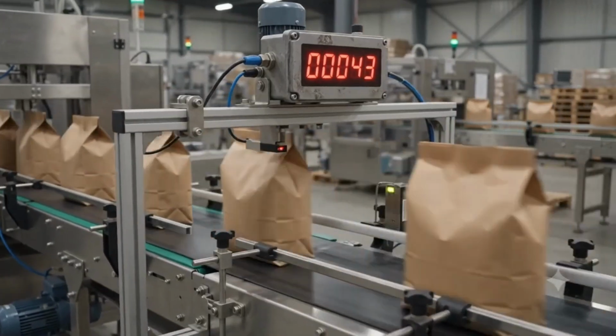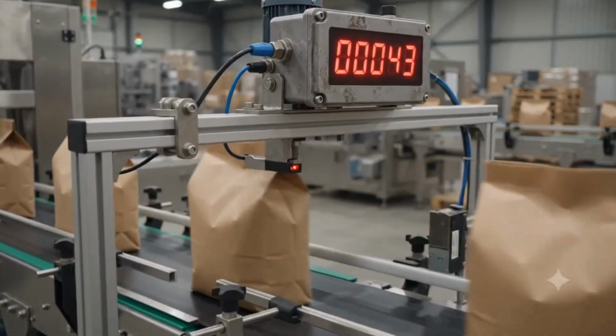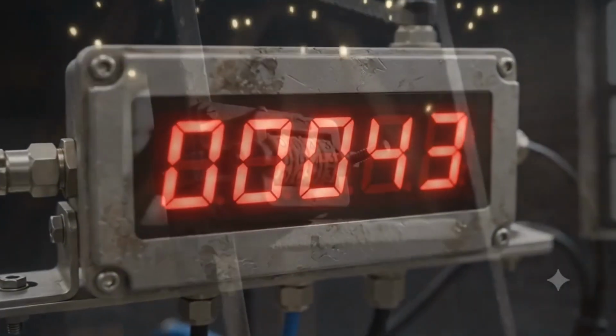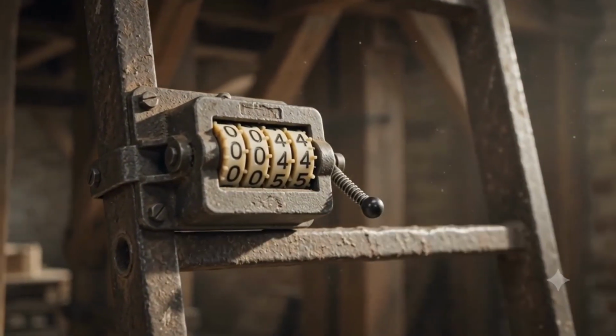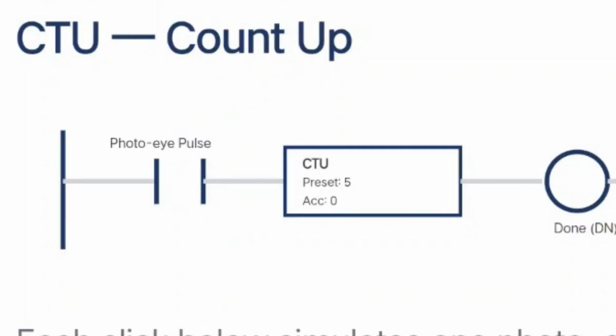If you've ever watched a bag counter on a packing line tick up one by one, or seen a batch cycle stop itself automatically after so many repeats, that's a counter instruction. Today, CTU and CTD, and the reset trap that catches almost every beginner.